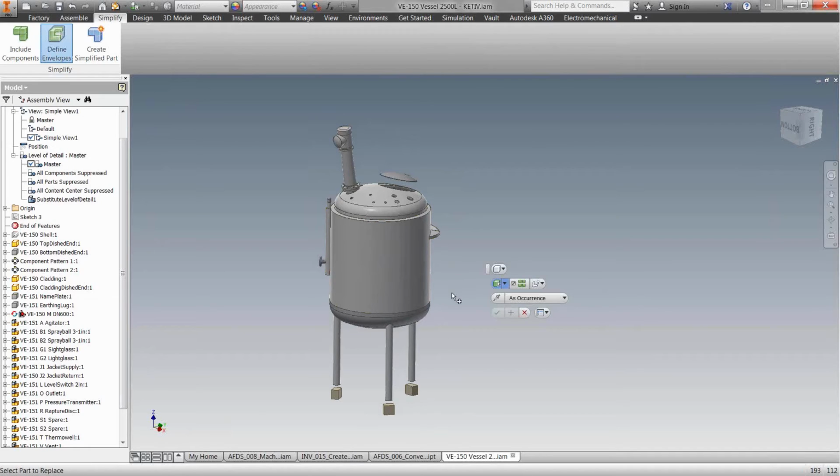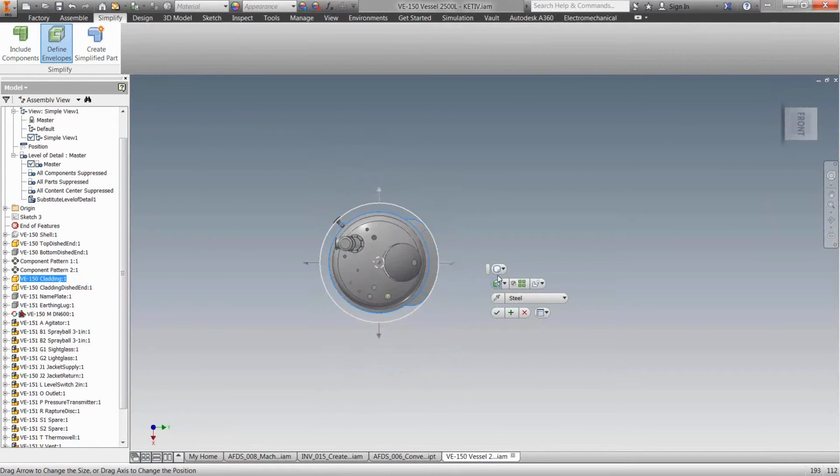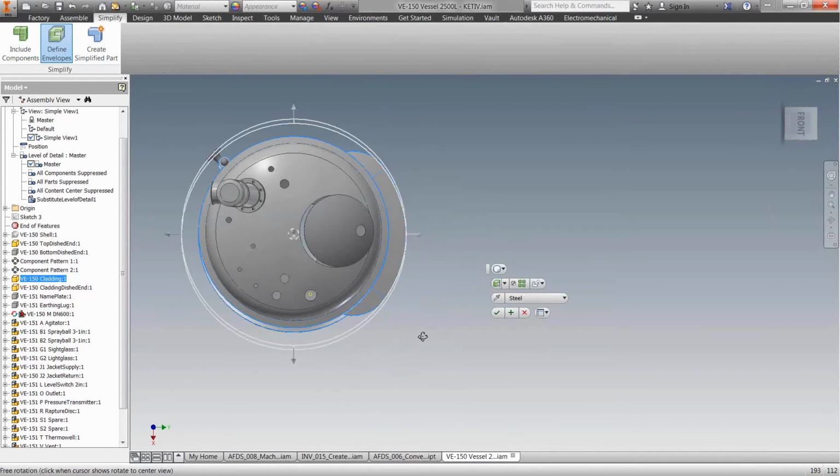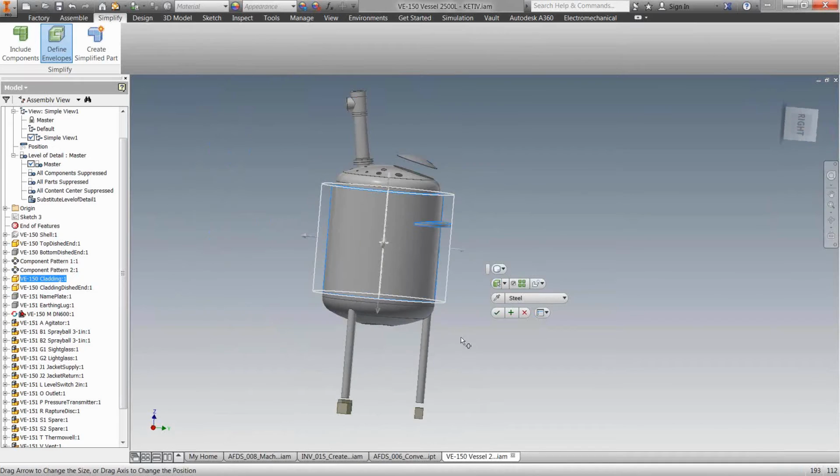And what this tool does is it takes an existing object and simplifies it to either a rectangular bounding box or cylindrical bounding box. So I'm going to go ahead and go to this one, right? So this object, obviously I don't want to make it a box, so I'm going to hit escape here for just a sec and kind of restart that. I'm going to switch first to bounding cylinder. And so now when I pick this, what it does is it tries to resize that cylinder to the outermost boundaries, right? And I can kind of take over and override that.